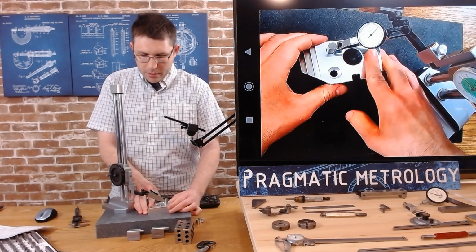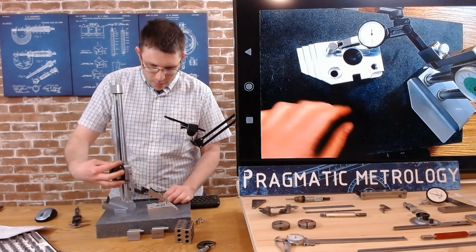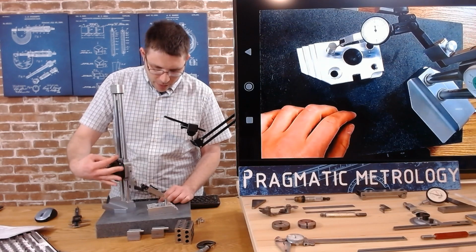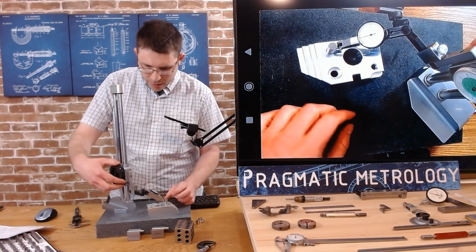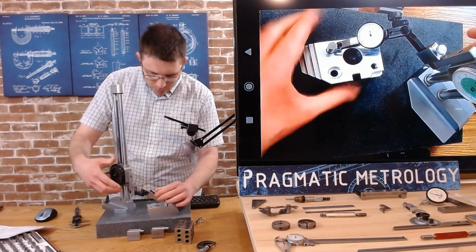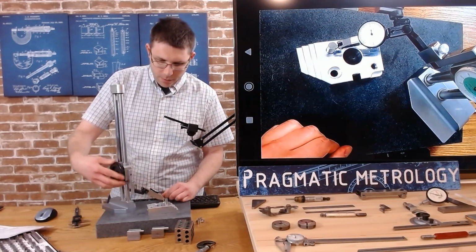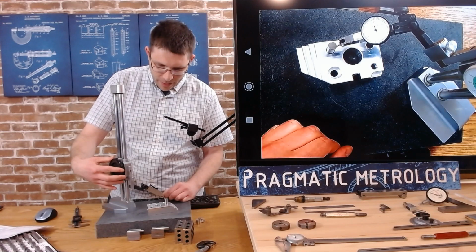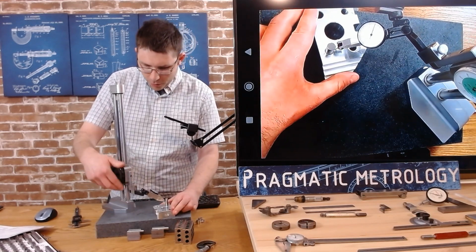So why don't I do it again? So I got about a 1/2 thousandths. I think this was the original orientation I did. Oops. I went too far with the indicator and bumped it. So I'm at 0 and rotating up, and I got about a 1/2 thousandths. And now I'm going to rotate my part and check another orientation.